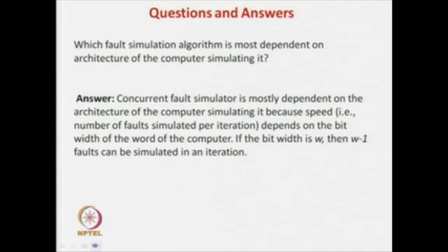But in event driven simulation, we remember whatever we did in the previous iteration, and only for the small changes for a fault or a pattern in some regions of the circuit, only there we do the recomputation. So, what is the advantage and disadvantage? Obviously, event driven simulation is faster because you do not recompute anything redundant, but at the same time you have to remember the values from the previous iteration. So, you need some extra memory, but the gain is speed because we avoid recomputation.